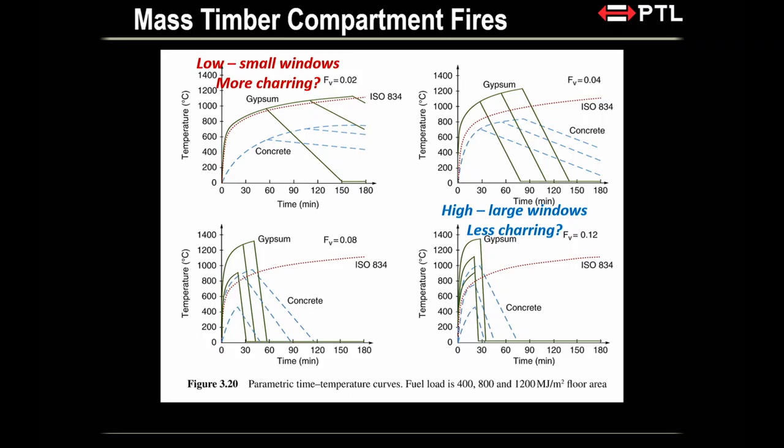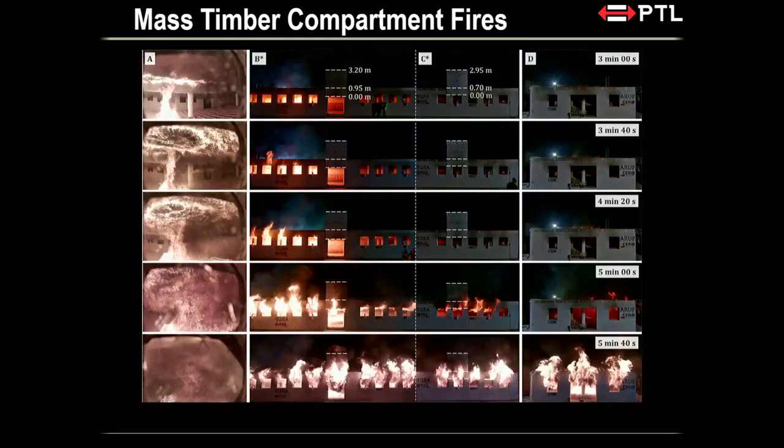And you think about this as an oven with the door fully open, right? So at some point, you're going to lose all your hot gas. It's not going to impact too much on your structure. So really, why I am showing you this here is because ventilation has a huge impact on the char that we are going to develop for mass timber and for your structural calculation.